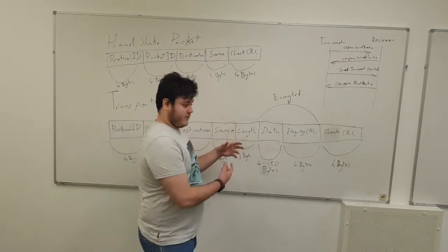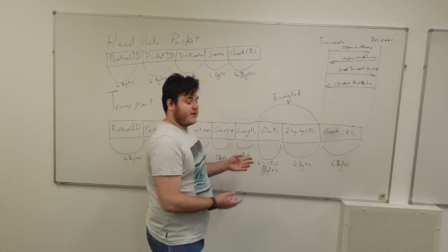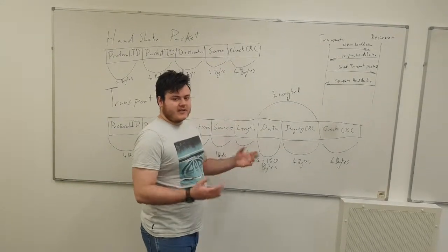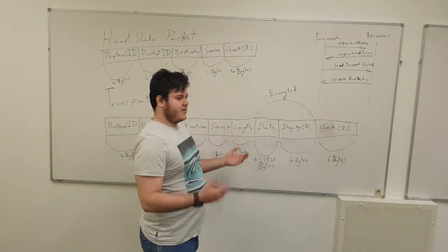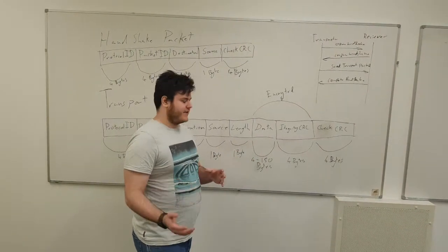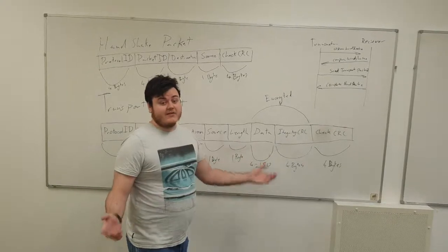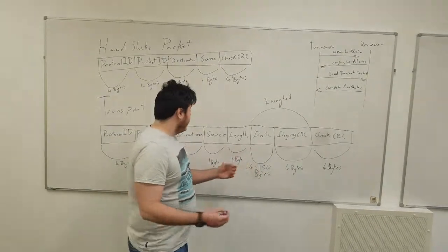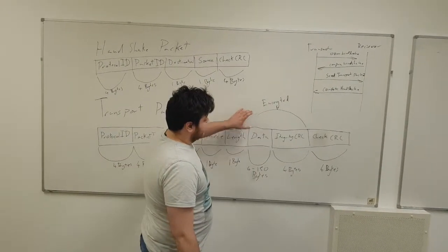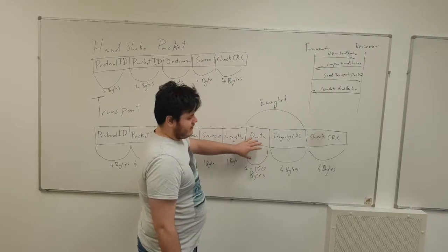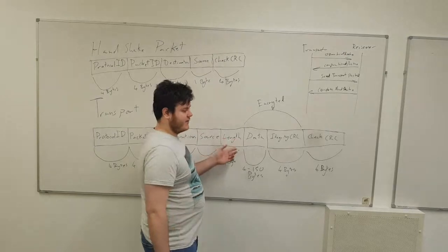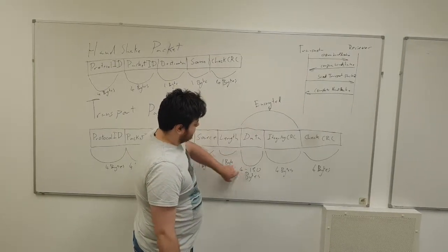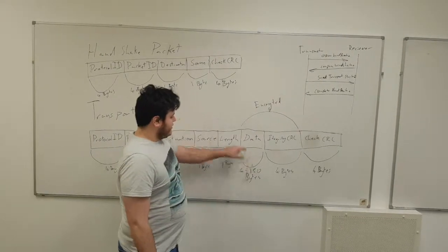Additionally here, because we wanted to create a sort of generic transport packet that can send whatever we wanted, we don't have to stick to just the readings for the sensor, we could possibly set commands or who knows what. So this one is just a generic packet, with a data area for raw data or any kind of packet that goes above that and relies on this protocol. So here we've just got 4 to 150 bytes, which is defined by this length.